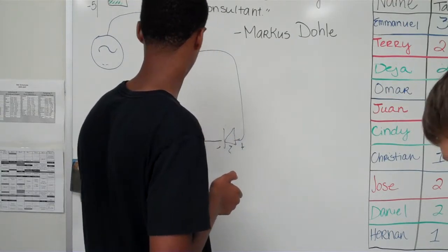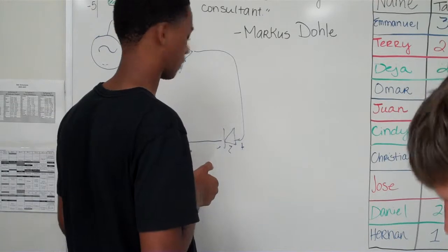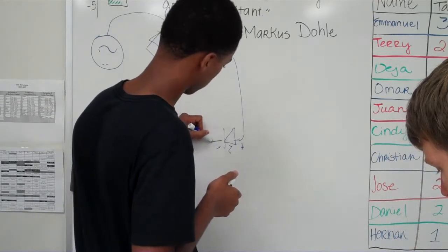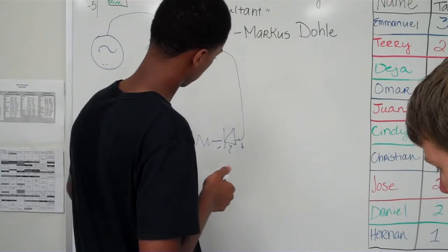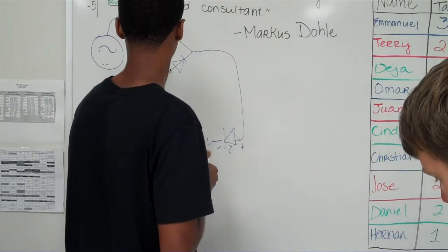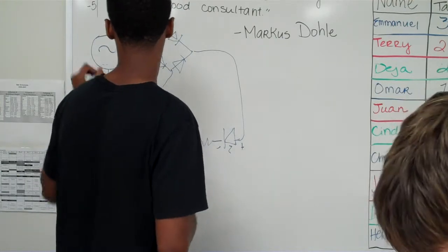And then don't forget your... What are you going to add here? What else do you need whenever you use an LED? That's right, a current limiting resistor.